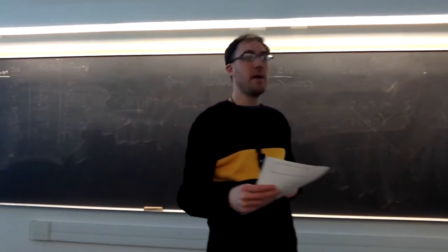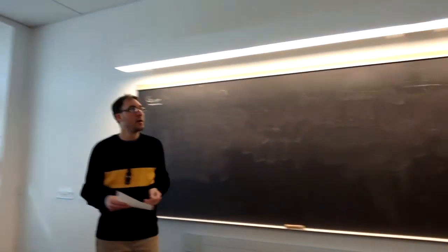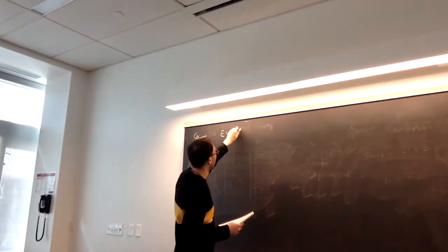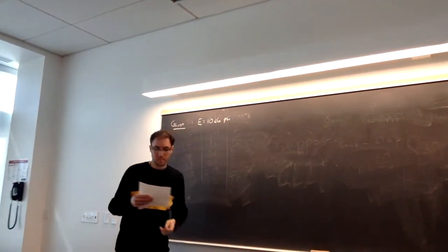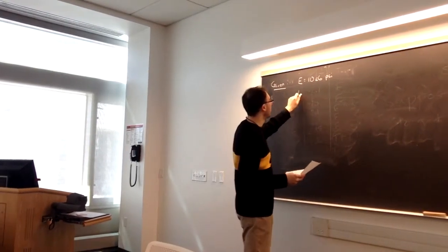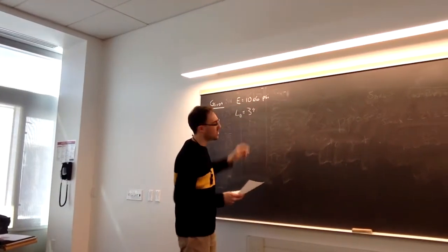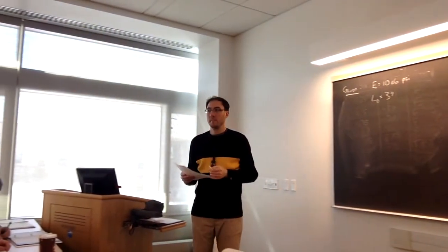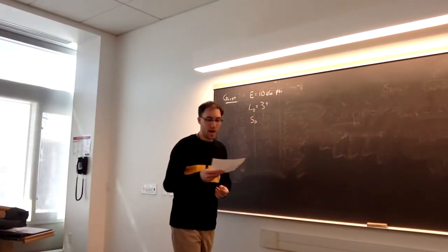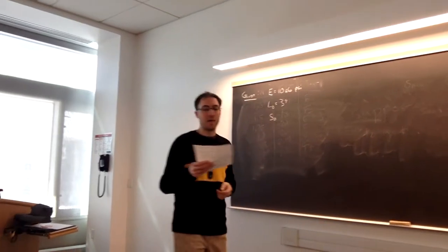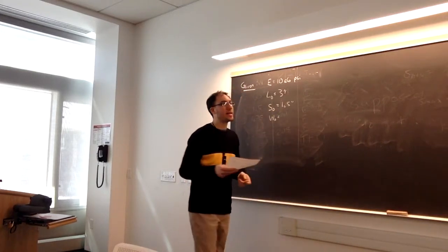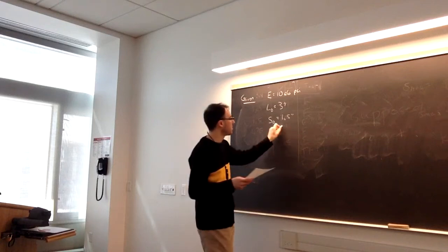This alloy of aluminum has a Young's modulus of 10 MSI, or megapounds per square inch. What I will call the length of it, the 3-inch dimension, is originally 3 inches. And then our original side, I don't know why I chose S, but for the 1.5 inch side, I'll call that S. It has a gauge length of 1.5 inches. And what I'll call the width is going to be the 2 inch.